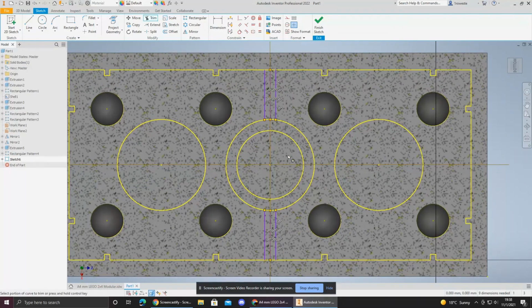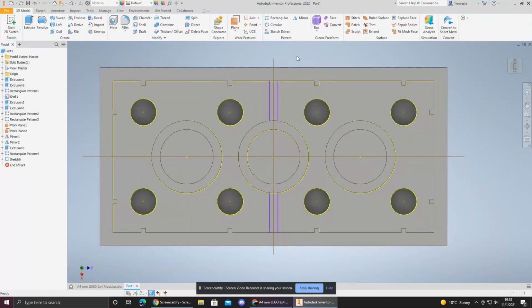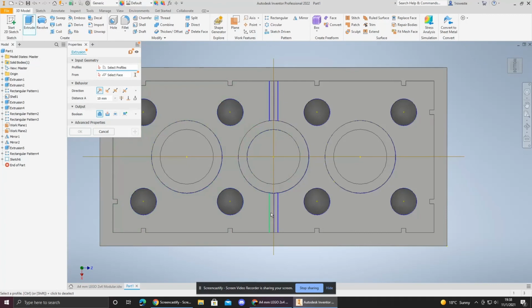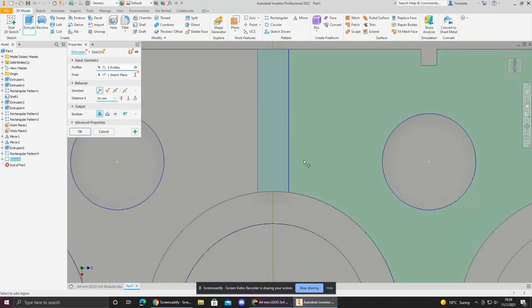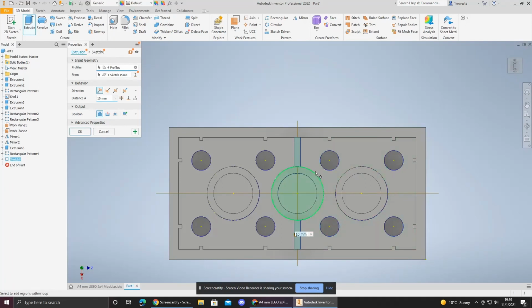However, this is an optional step, as due to you having projected the geometry, they have been selected as separate zones anyways. So honestly, this is simply for if you come back later and need to make an edit. Either way, we may now finish the sketch and extrude these lines. If one were to delete that center line, you would lose your constraints. However, you would only need to select 2 boxes.